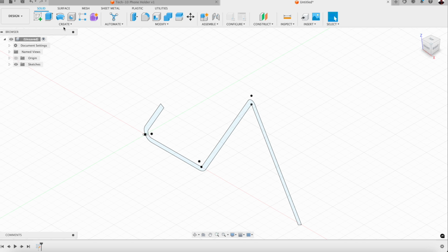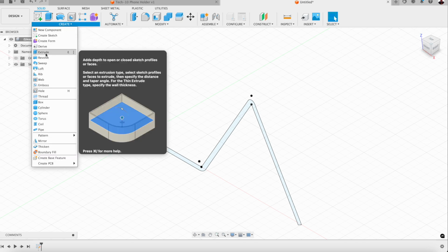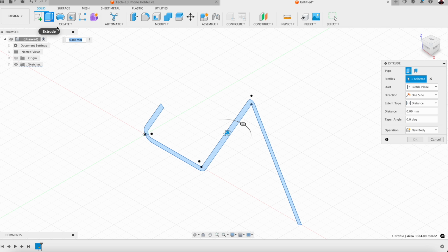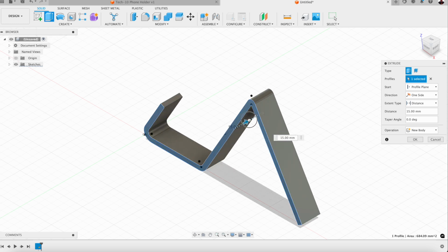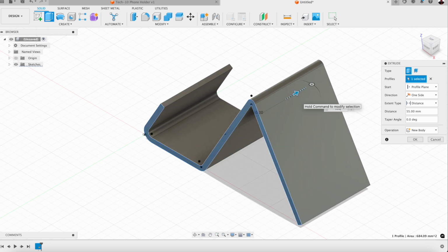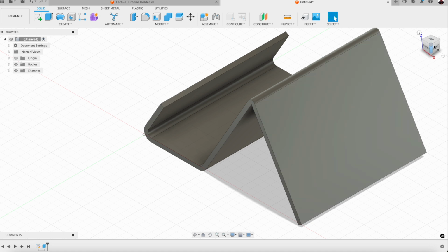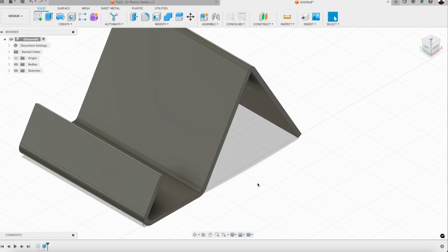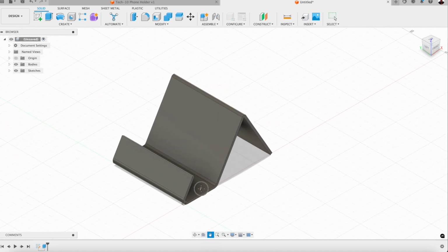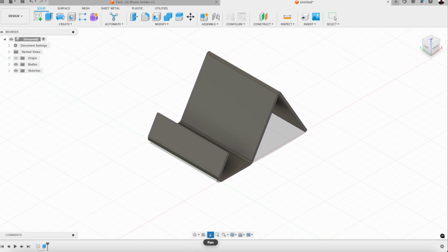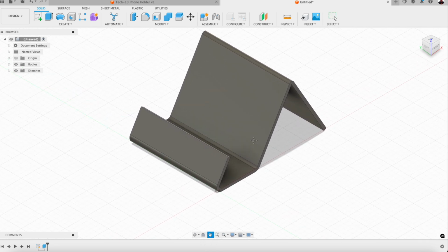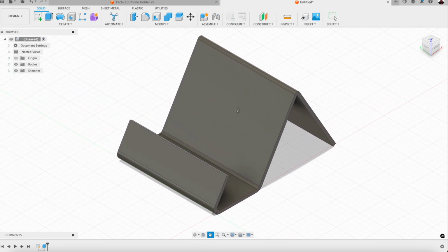And this time we're going to extrude, create an extrusion. Shortcut key is E, or it lives up here in the taskbar. Drag the drag handle out, type in 100, enter. And you can see here now that we've got the basic shape. All right, we can move it around with the pan tool. That's the hand there. You can click on the hand and drag your model around, or zoom in with your mouse to get it a bit bigger.